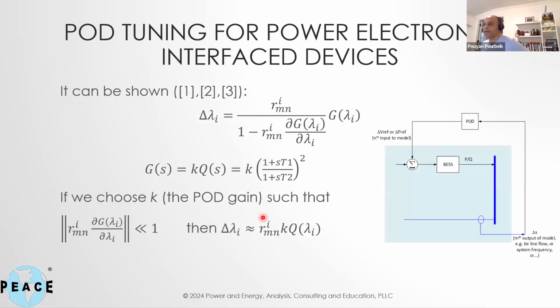So now, if you go through the math of all that, one of the things you can do is calculate what are called residues. That's what this R defines. I can calculate the residue using a standard small signal stability tool. Once I've developed this explicit small signal model and created my user written models and put all that together, I can calculate the residue from some stabilizing signal that I pick.